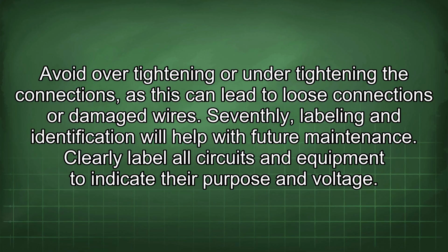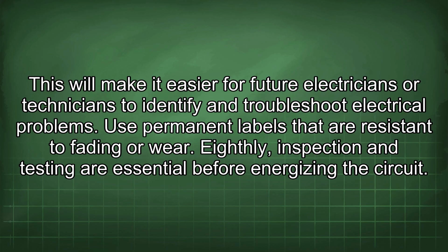Seventhly, labeling and identification will help with future maintenance. Clearly label all circuits and equipment to indicate their purpose and voltage. This will make it easier for future electricians or technicians to identify and troubleshoot electrical problems. Use permanent labels that are resistant to fading or wear.